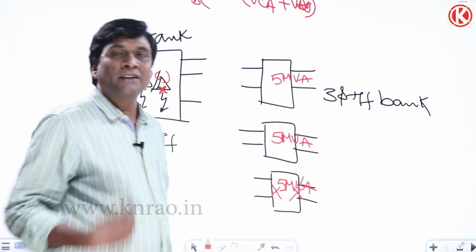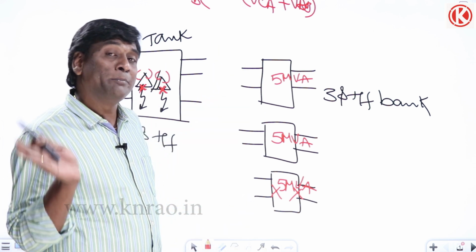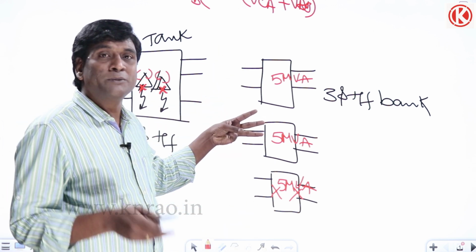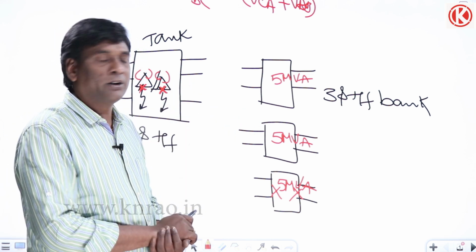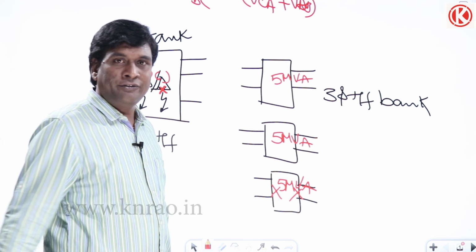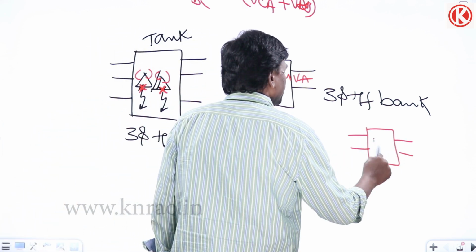Okay, my capacity backup should be there. So out of these 3 transformers, how much should be the backup capacity? Because these 3 transformers may not develop the fault simultaneously. Okay, so maybe one of the transformers may fail, so my backup can be only a 5 MVA transformer.